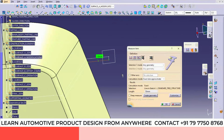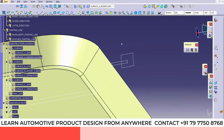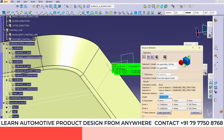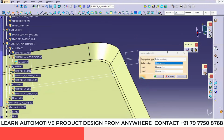So first I'll check the length. This is 10 mm, so a 10 mm length surface is required. Then the angle also we'll check from any geometry, this to this. This is 128.546. Copy this angle. And then here we'll create a boundary because the complete edge is required, right? This edge.